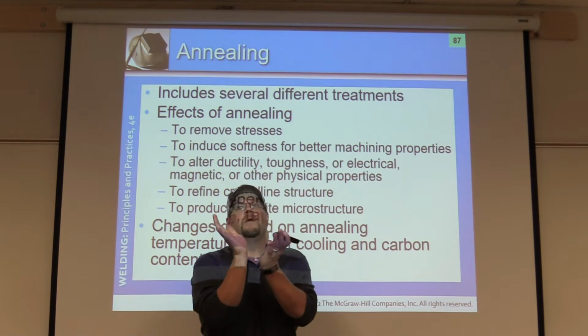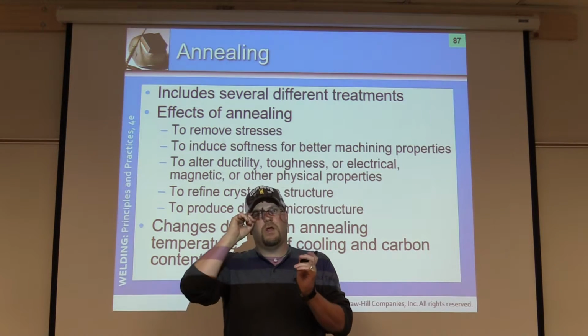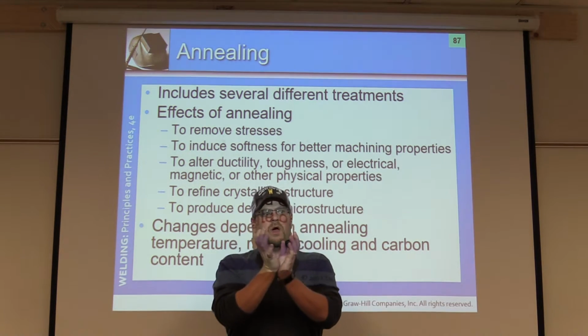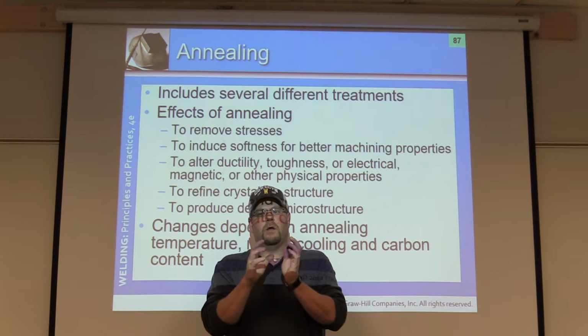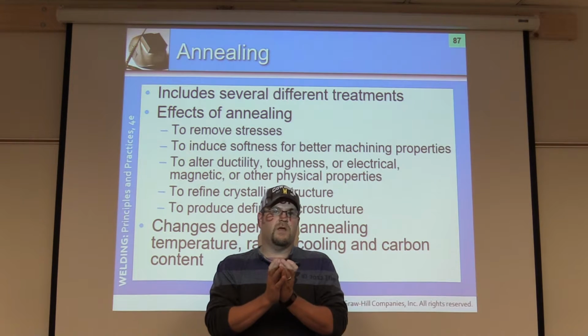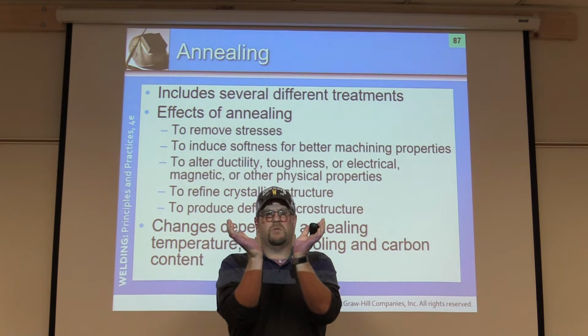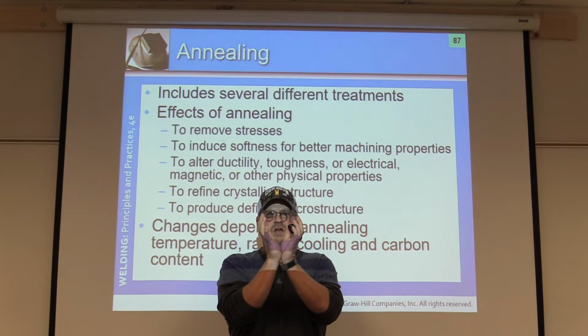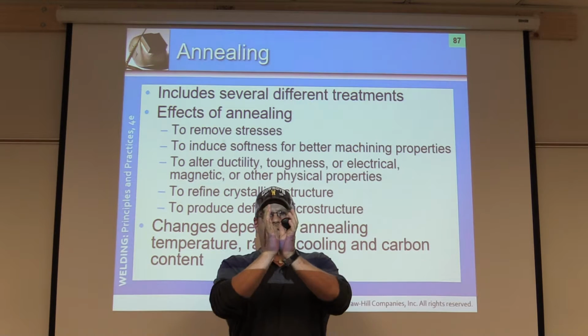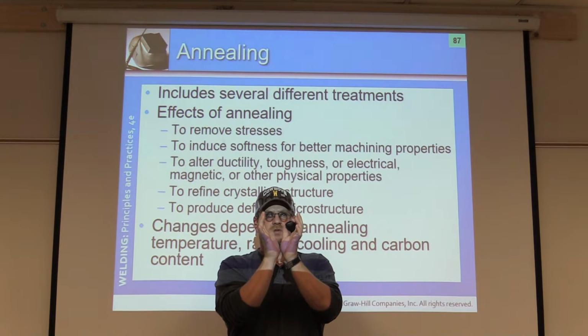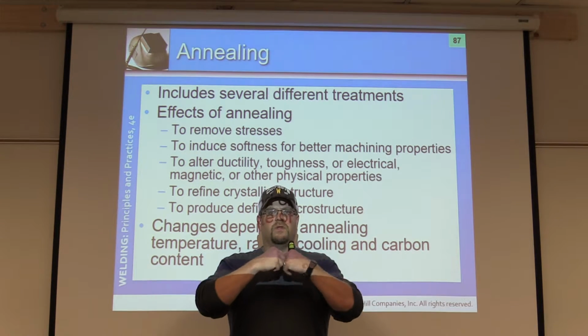So stress relieving, anything, especially a large piece of weld that has undergone a large amount of welding, even thin material. Same thing, it can be even thin material as well. Okay, I shouldn't say just large. But anytime we weld, we confine stresses into it. Weld pools contract, stress, and it'll start to pull. Even if you don't notice it, it will create an internal stress, kind of a tension within the weld.